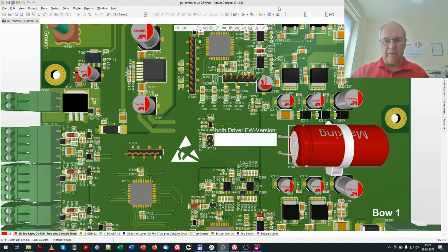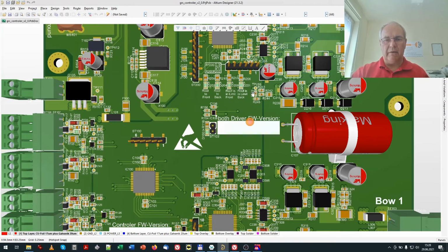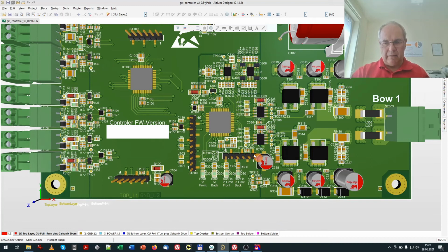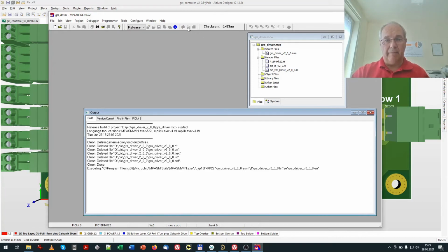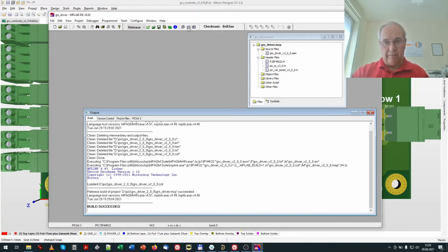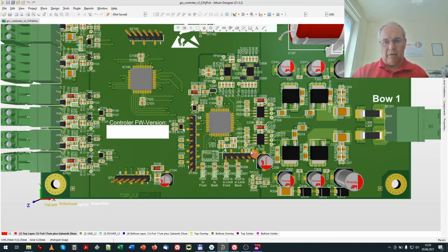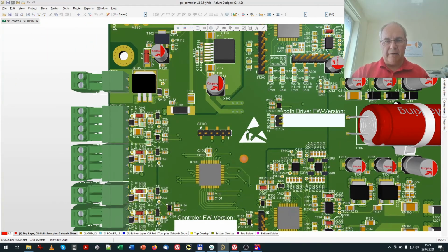Go back to the board, plug off here, plug in here, the same orientation. Go back to the IDE, click build all again, the same procedure: compiling, programming, verifying. Go back to the hardware, plug off, plug in here, also the same orientation, pin 1 is here.